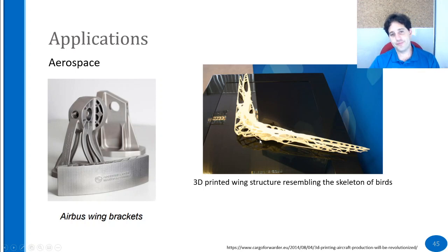And taking this a step further is the wing structure. Now, this still doesn't exist as far as I know for available planes and consumer level planes, but there's a lot of work going into designing wings and hulls of planes to be very sparse and have this very involved geometry, because like the cube I showed you at the beginning, if we can make this a lot lighter and yet as strong as the solid counterpart in the specific directions where the stress will be, we can save a lot of energy.